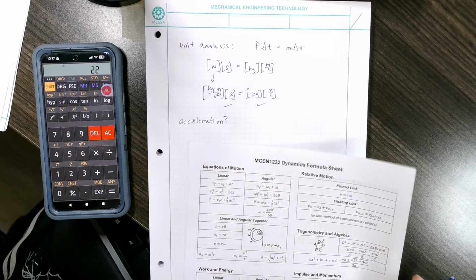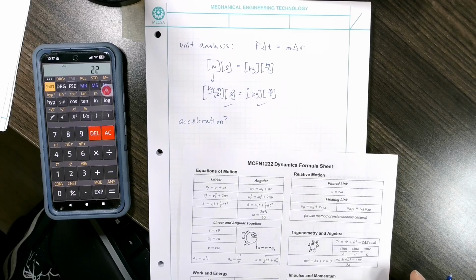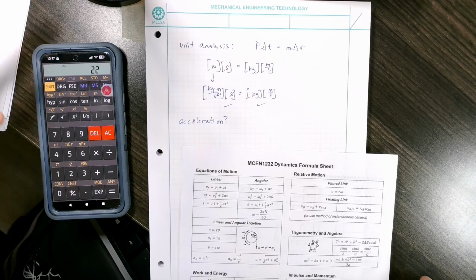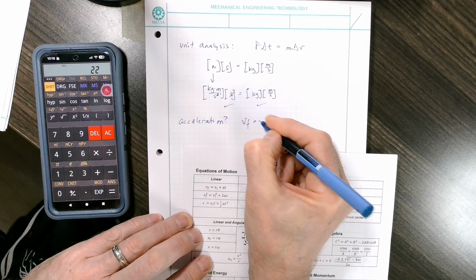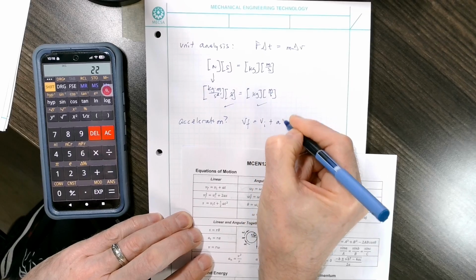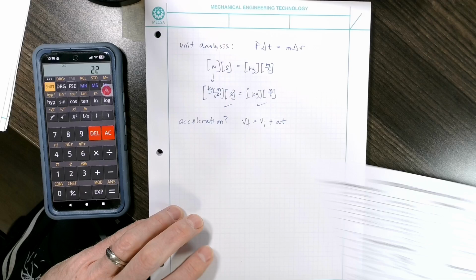Don't. It's not 9.81. That's no. This thing's not in free fall. It's a machine. The acceleration's subject to the mechanics of the machine, the gear ratio, and so on. Acceleration. Use kinematics. V final equals V initial plus AT, same thing. You just go shopping for an equation that lines up nicely.